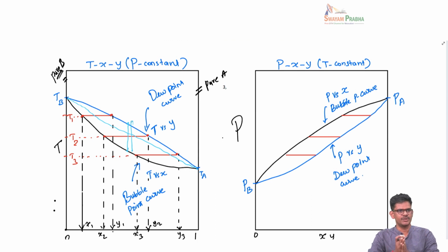A two-phase mixture would have a range of temperatures, and that range depends on which composition you are talking about. When I am looking at a very small a and more b, that range is very narrow. When I go to this side where I have more of a and less of b, again the range is different, magnitude wise. That's a very important point to understand.